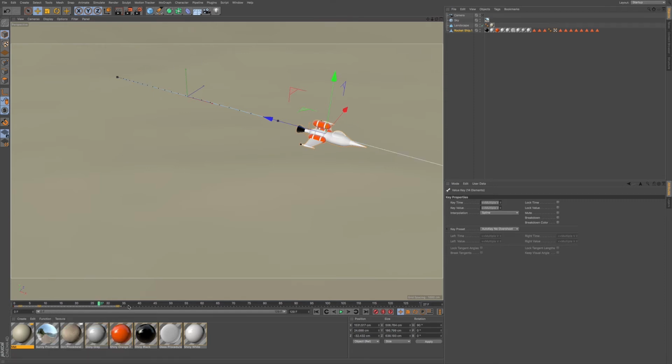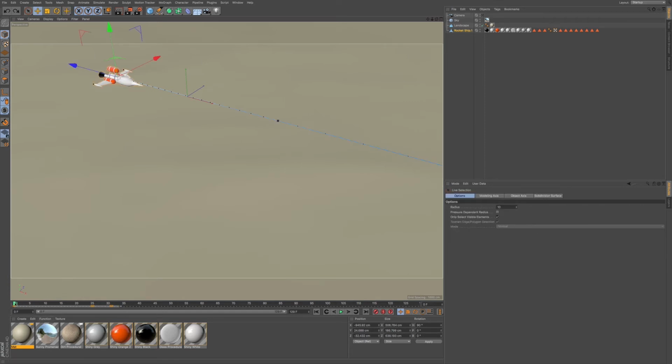So the next thing I want to talk about, since we're on this highlighting of these keyframes, is that you can drag and select all the keyframes, and then you can right click. You have an option here, if you go to edit, you can reverse sequence. So there might be a situation where you're animating, but you feel that the sequence can be reversed and it will give you a different type of look. So if I play by pressing my space bar, you can see that it comes in reverse. So it's just another option for you. So I'm going to undo, go back to our original, and we can play that.